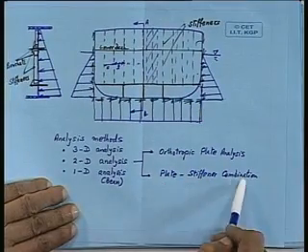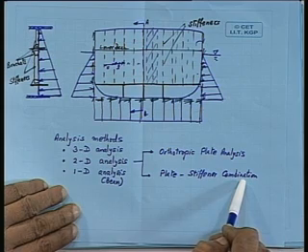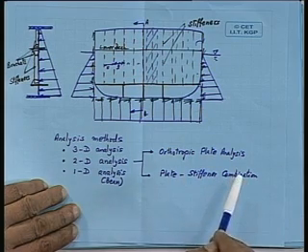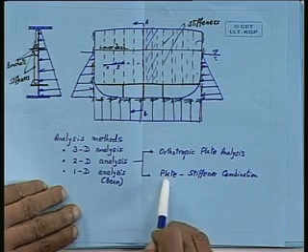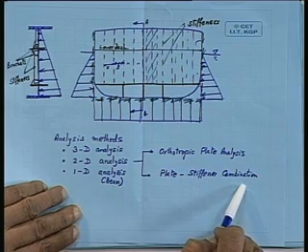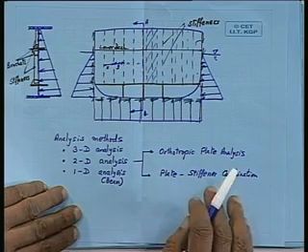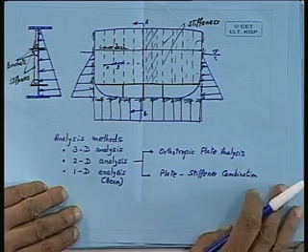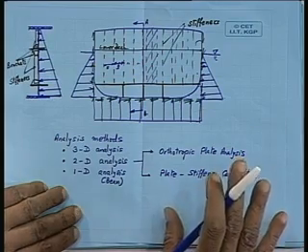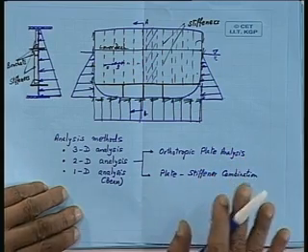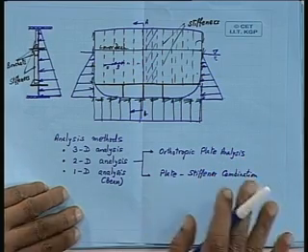And on similar lines, people have tried to use this plate stiffener combination, and that is also not very successful. But plate stiffener combination on the basis of what is known as the numerical method of finite element analysis gives you somehow a true picture of the deflection and the stresses within the structure at all desirable points.